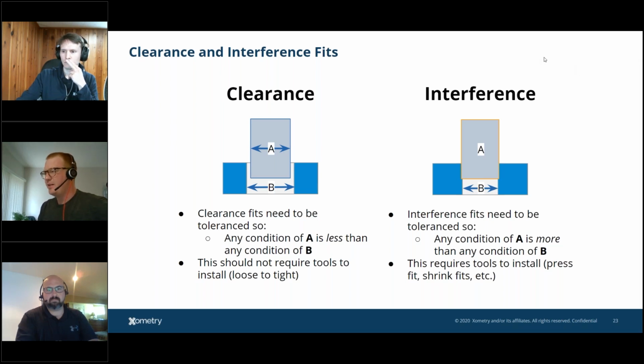And there's been a lot of engineering precedent for how to design fits. Depending on what unit system you work in, there are ANSI standards that define fits. They go from things described as loose or free running, to positional fits, which are a little bit tighter, to force fits, which would require that a mating part be pressed in or either heated or cooled to assemble properly. And on the metric side, there's an ISO standard that defines how to call out and specify your fits.